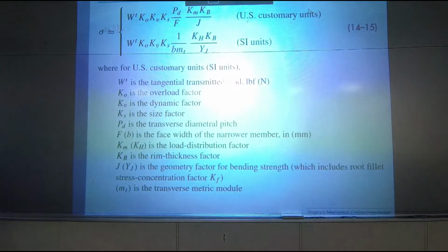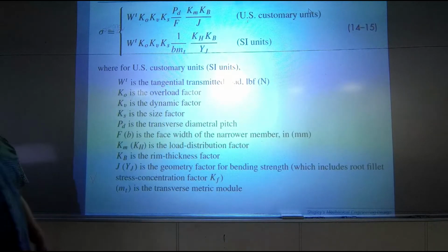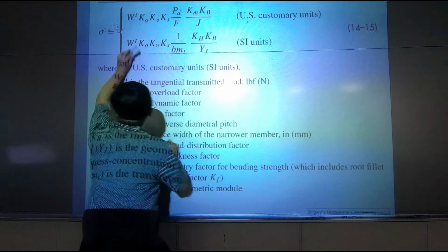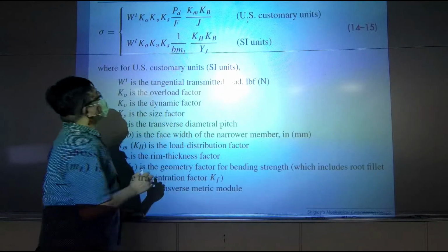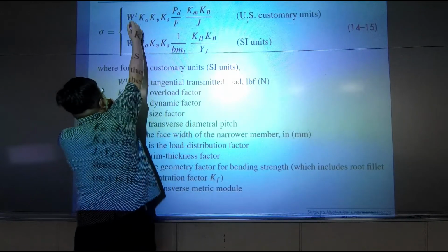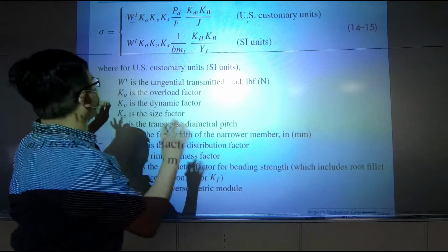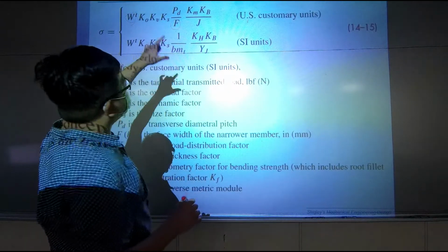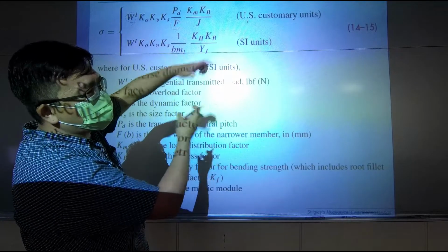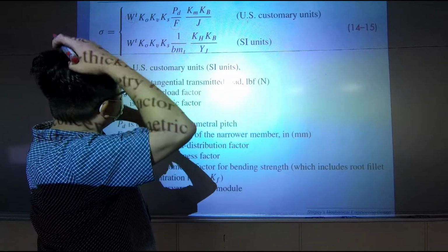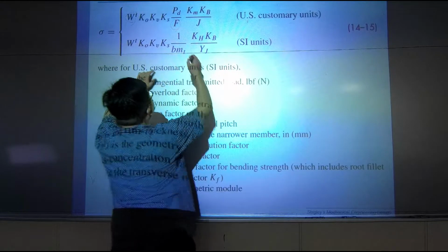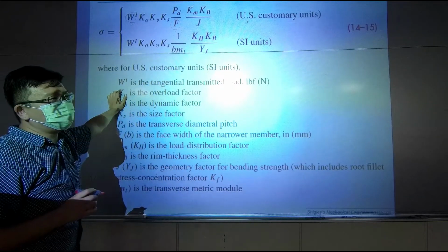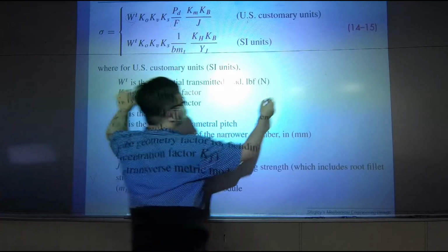The textbook tells you at the end, the stress equation should look like this. And you can tell, okay, I still have my transverse force, I have my face width, and the book kind of reorganized the equation a little bit. They don't use small p anymore, they use PD. PD is the diametral pitch.